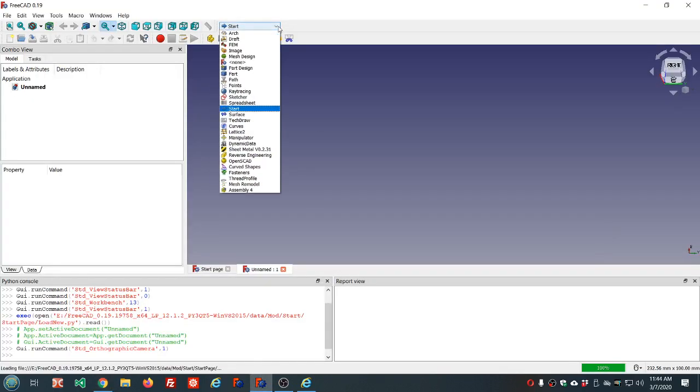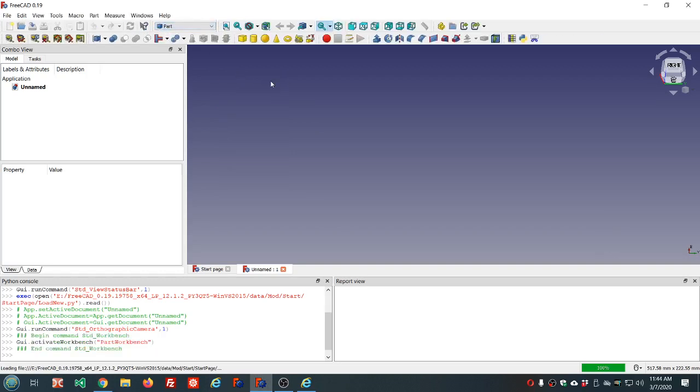So I'm going to do this in the part Workbench, not in part design, because I want to make an array of sketches representing that profile and sweep that profile around. Actually, loft from sketch to sketch, each copy being rotated slightly.